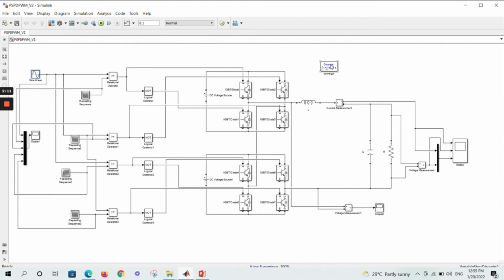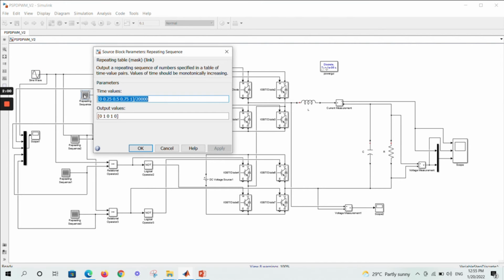And then next, in our power GUI here, we set it as 1 microsecond, which I also got from the suggestion from my SV. And next, we set our repeating sequence. In this repeating sequence, we are setting the time value, and actually this 2000 is the carrier frequency that is fixed for all types. I will not change the frequency here, but I will change the frequency band. I will change the frequency band to make differences in every type of the method that has been created.